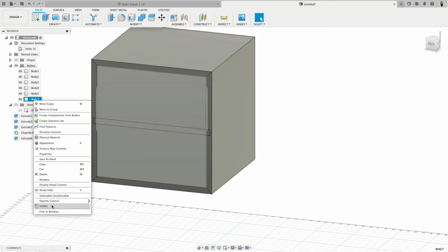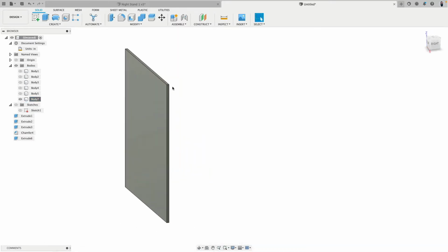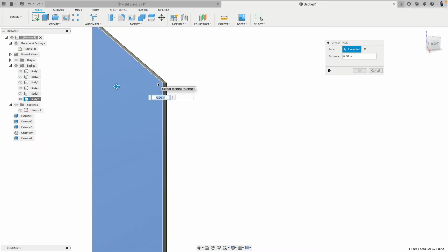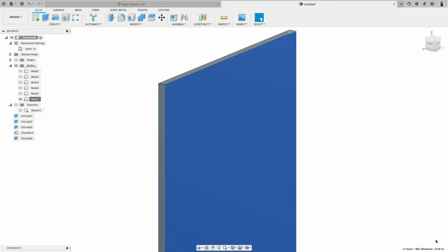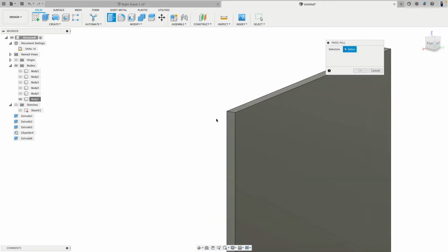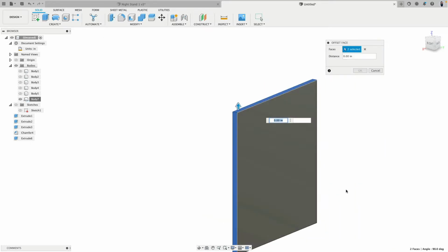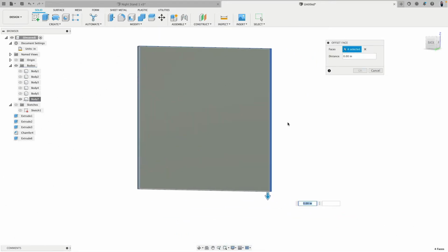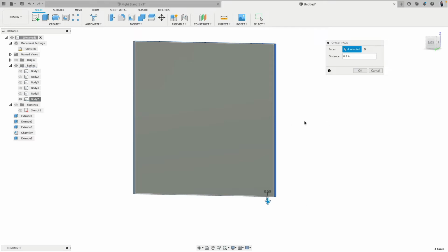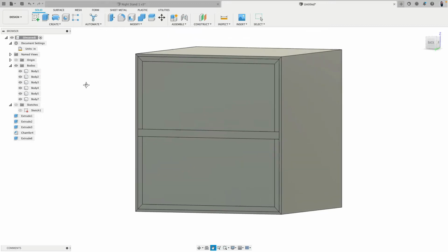This piece now, I will isolate one more time. And I will actually give this another 1/4 inch material. So this is now 1/2 of an inch, as you can see in the lower button. Then go to expand, and we select all these edges, 0.5 of an inch. We expand it. So it's bigger. Then we can show everything. And there you can see how it overlaps.